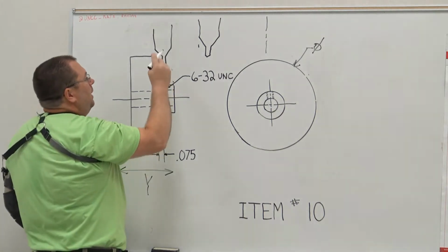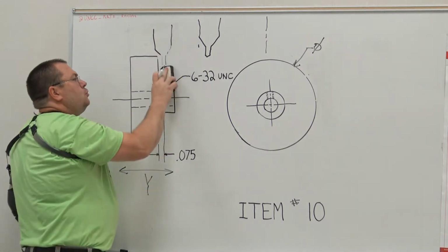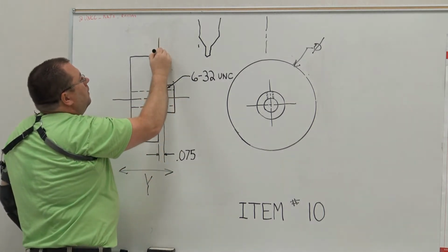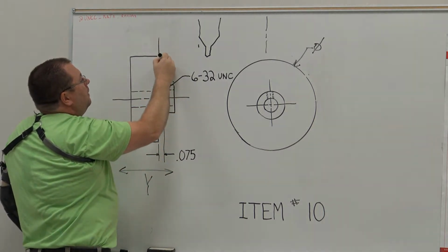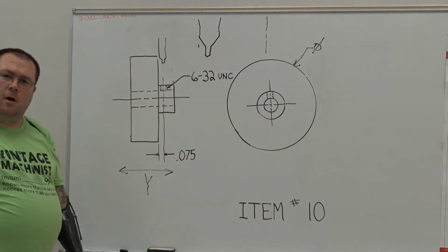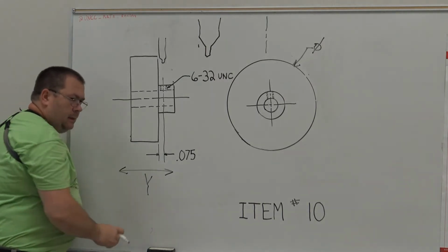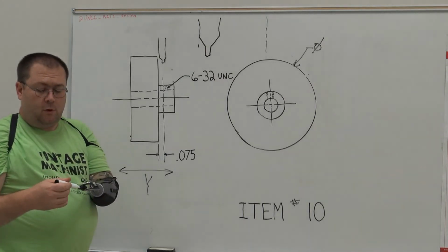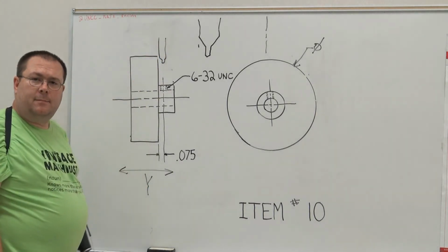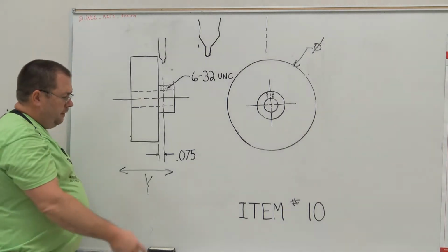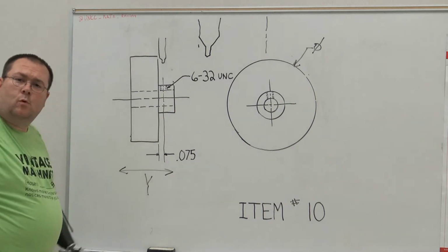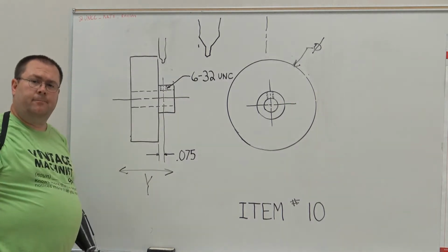When you get into the shop and you buy your tool kit, we have supplied, or we've gotten the toolkit set up now with a much smaller center drill. That smaller center drill is a number 1 center drill. The number 1 center drill's body is 125 thousandths in diameter, or 1/8 of an inch. Well, 125 is less than 150 thousandths. So you can use that number 1 center drill to put that spot in, okay?